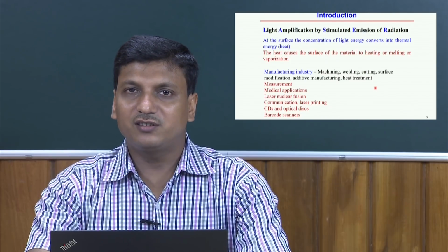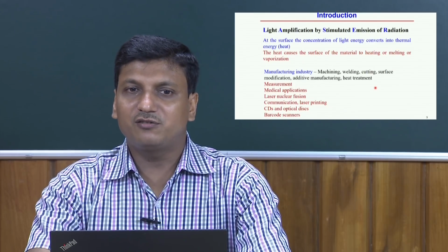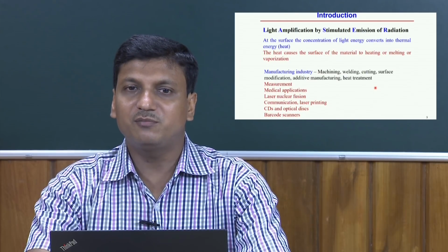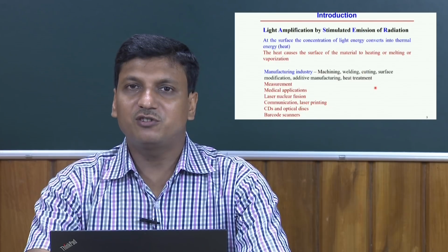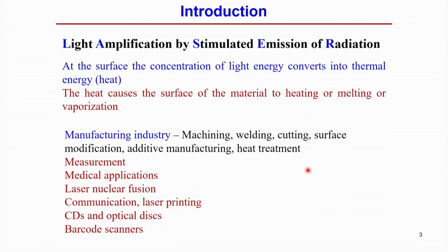We know that there is a huge application of the laser. Even in the manufacturing industry, in processes like machining, cutting, surface modification, additive manufacturing and heat treatment, there is a huge application of the laser. Here the laser is used as a source that can heat the surface whenever required, either to melt the surface or to vaporize it.